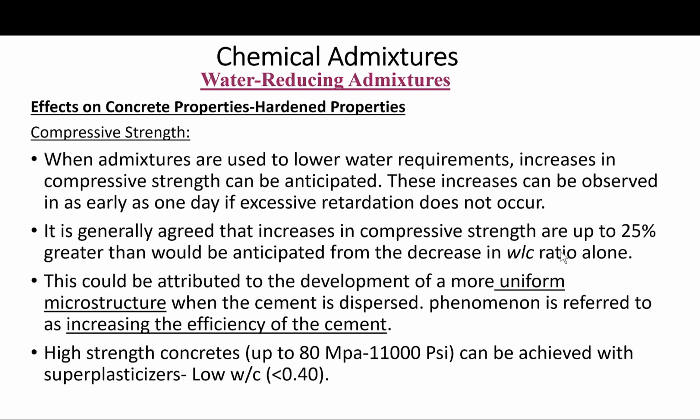So again, the point to take away from this: when we reduce the water cement ratio or the water content, we automatically increase the strength and refine the microstructure by decreasing the void content of the concrete or the paste matrix, and that by itself is considered a great enhancement to the concrete durability and performance.